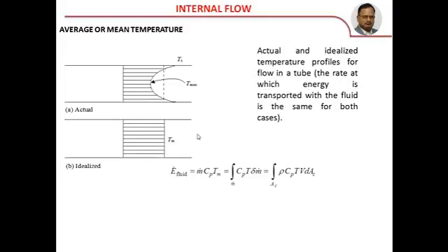And it is idealized as a rectangular shape like this. So the energy entering into this is m Cp Tm. Assuming that the energy at 0 degrees centigrade is 0, you can write m Cp Tm, which is equal to, for this one, take an elemental strip of delta m passing through it, that is delta m Cp T.